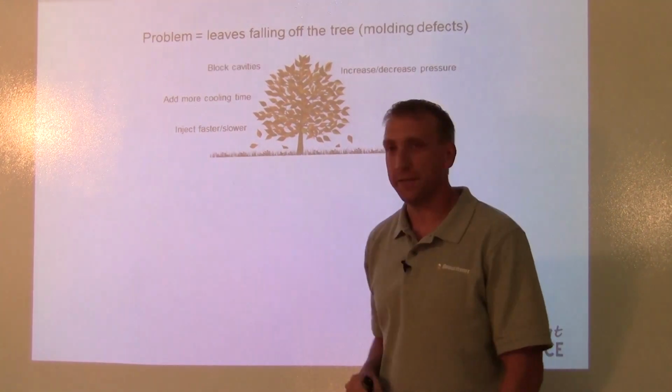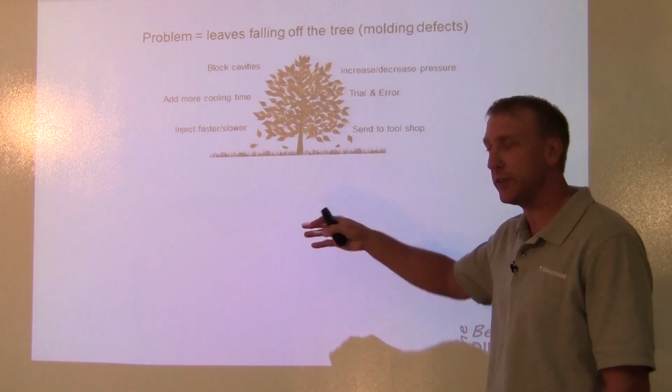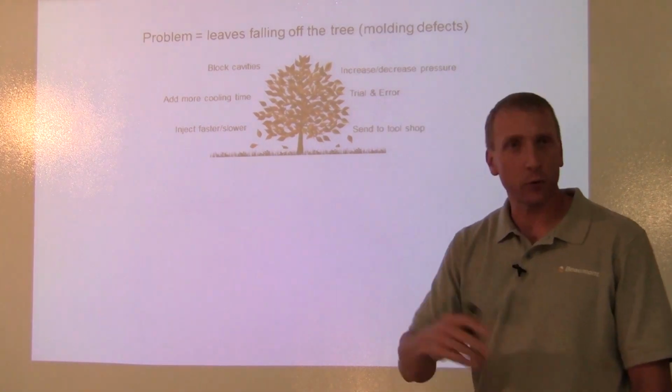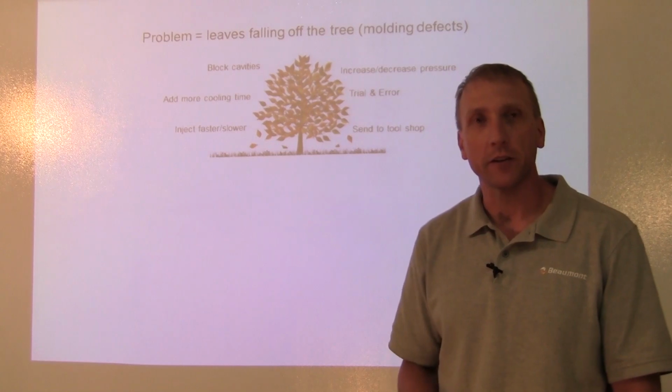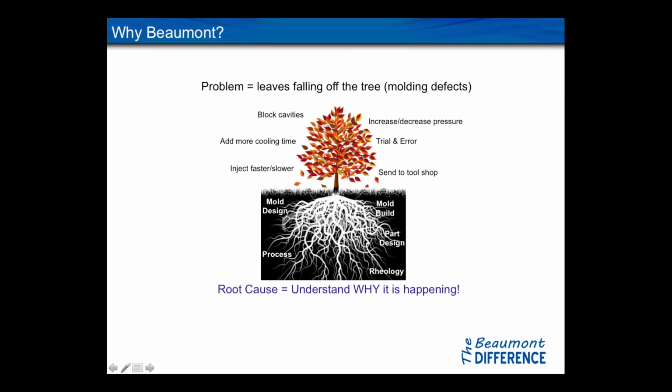Well, people try to inject faster, slower, add more cooling time, less cooling time. They'll block cavities. They'll do a lot of trial and error, send the mold back to the tool shop and hope they fix it. What we want to focus on is the root cause.